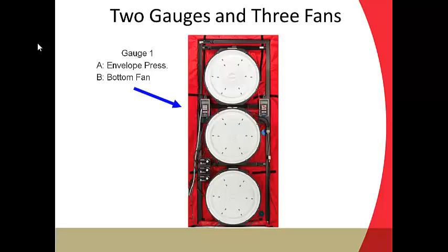And then we've got just a generic pressure. So maybe you want to be measuring an attic or garage pressure during the test, but that's not a pressure that needs to be within 10% of the induced pressure. So you've got 3 options for pressures, and then depending on which fan you're using, Model 3 or Duct Blaster fan, you have the option of setting up each channel that way.